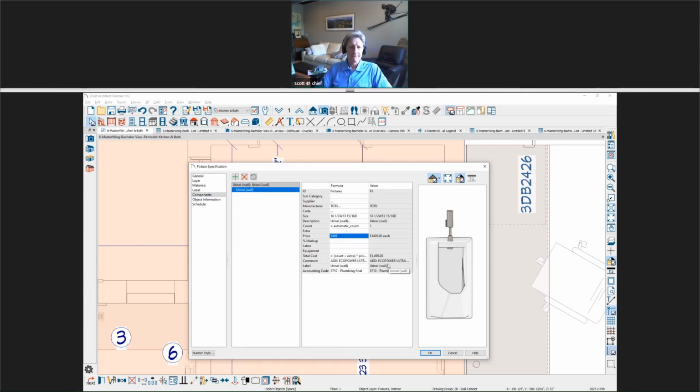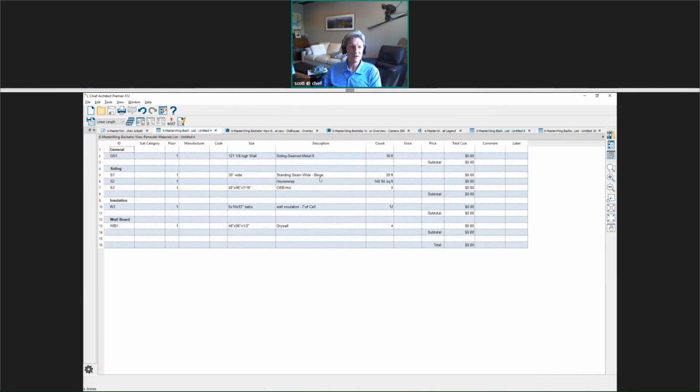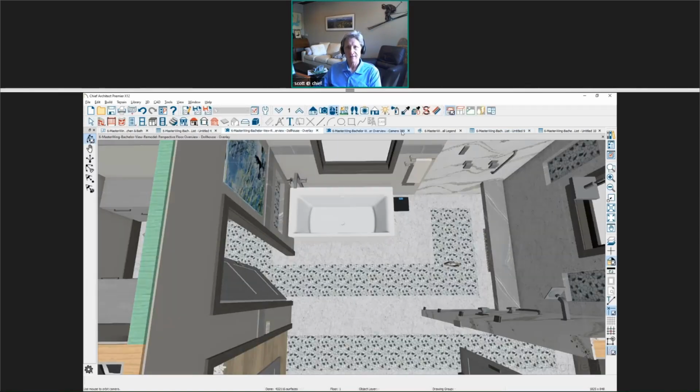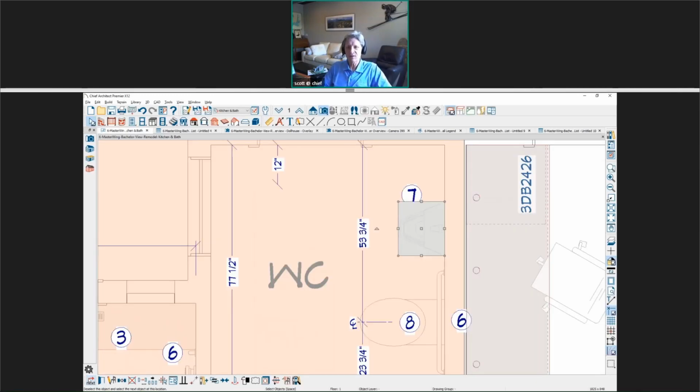Okay. Hey Scott, this is Adrienne. Have you been able to show the find object and plan feature in the materials list? I think that's what I just did right there. Oh, okay. Go back to the materials list, and of course I've got a bunch of them open now. And here we were. And again, you click on the unit, you click find in plan, which is in the far bottom left-hand corner, and then that pops it open right directly to that object. That's a very handy feature.